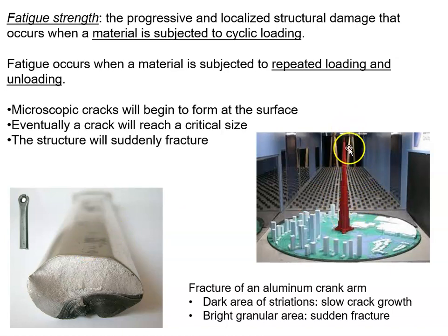So this would be a good example of cyclical loading. Not steady and regulated the way that the hydraulic press in the IKEA showroom is loading the chair. And if this is in the hand of a human being, it would not be cyclical loading like the hydraulic chair either. If it's a wrench in a hand, it varies. So it could either be uniform and cyclical, or it could be changing and cyclical. But wind bearing on a building could cause fatigue as well.